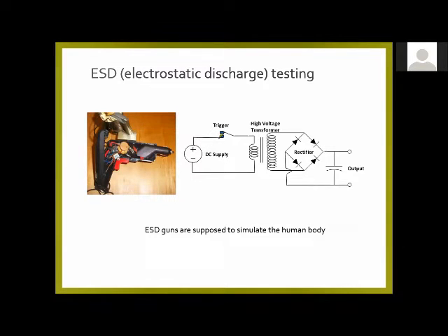And you can generate a high voltage, put it on a capacitor, and discharge it through the tip of the gun. And we made charging for the gun using transients from a switch. So we pump the switch a few times and generate a high transient from the switch, and that charges a capacitor, and we then discharge that to whatever we're doing.